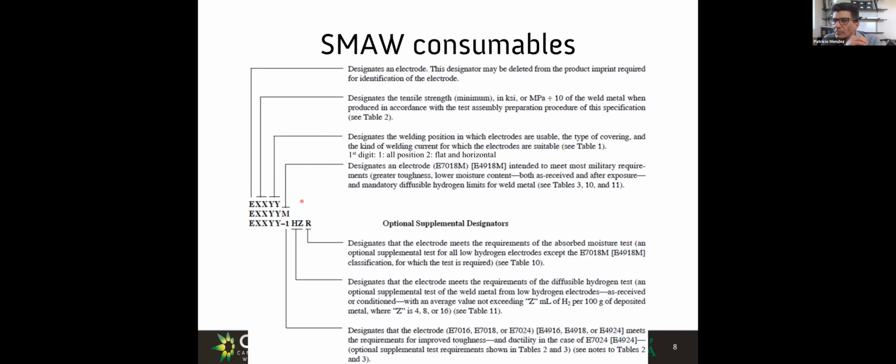Okay, I have a question. The question is if the current and voltage will be the same in ER70S-2 and 70S-6. And the answer is yes. For the case of MIG, if you use the same wires with the same currents, you see pretty much the same, except that the metallurgical result after the weld has been done is going to have different hardness, or if it is dirty, you would have gotten better cleanliness. But yeah, current and voltage would be essentially the same.